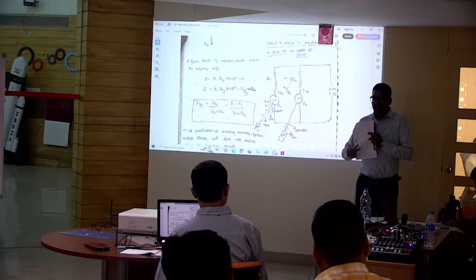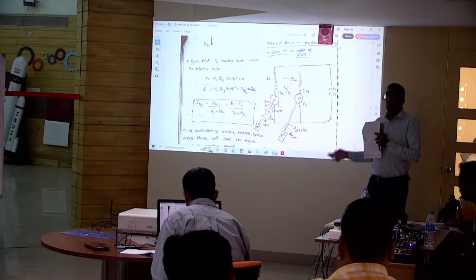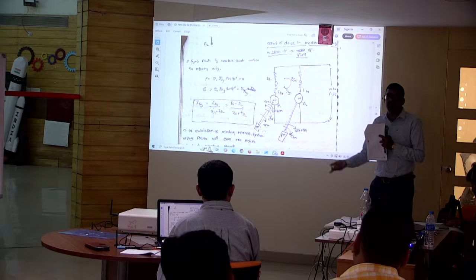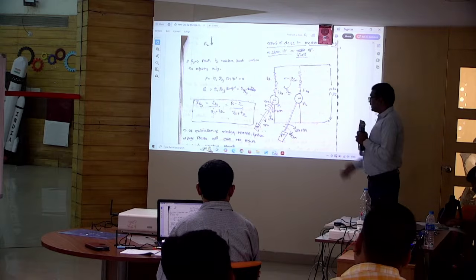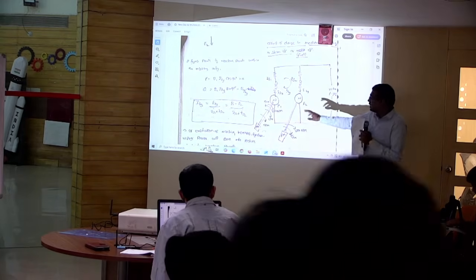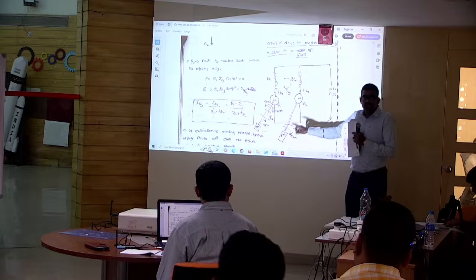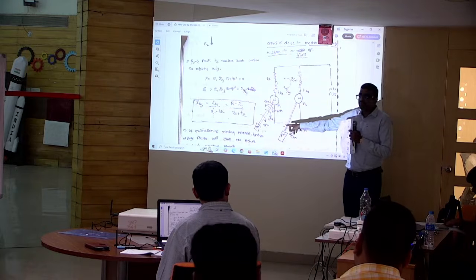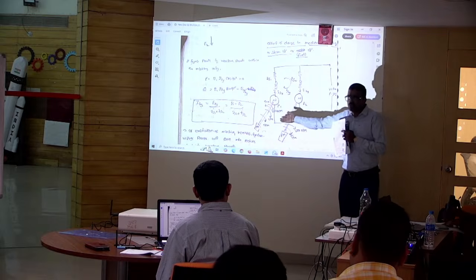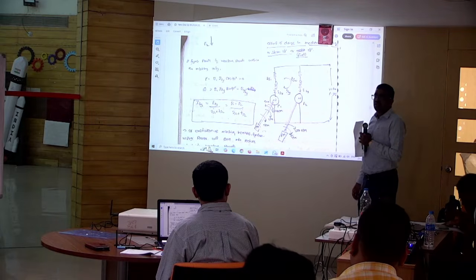This current is trying to synchronize the machine set, both the incoming and the existing. Now, in what nature will this synchronizing current be? We will see. Upon changing the prime mover input, if I keep it constant, the speed is the same, say 1500. Now if I change prime mover 1 to say 1600, then what will happen?